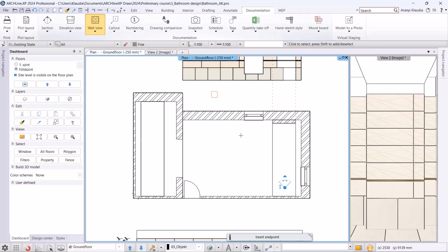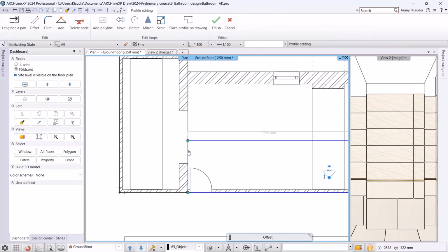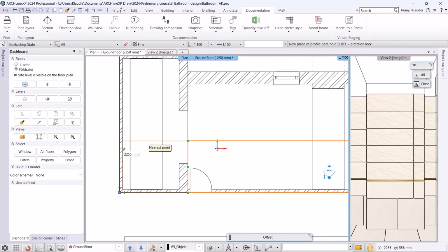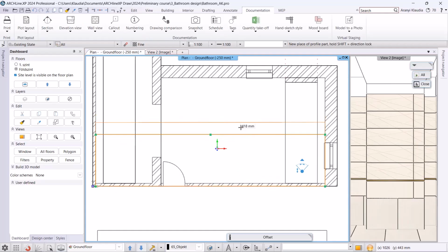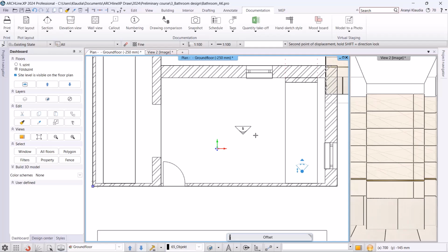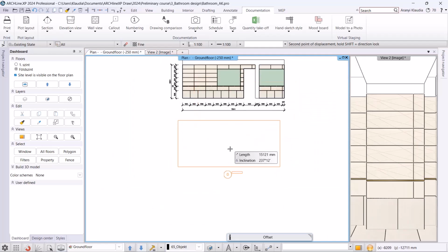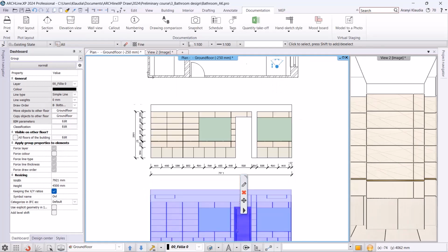I run the Single Wall View command. I click on the wall and then use the arrow to set the direction of the view. A blue rectangle appears, allowing me to set the area which will be on the wall view. I press Enter to accept it. The wall view is created and I'll place it on the floor plan. The wall view is a group. It can be dimensioned by entering in it.